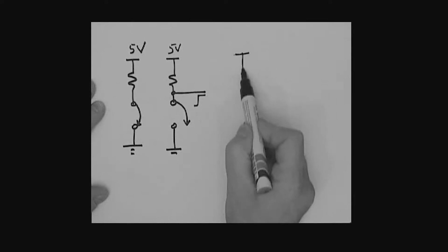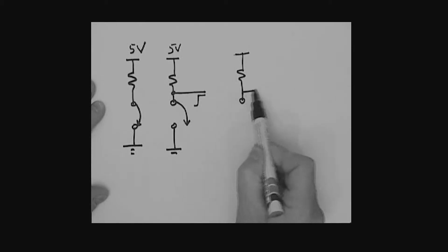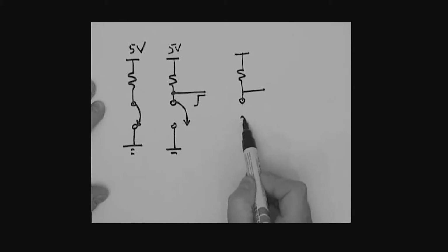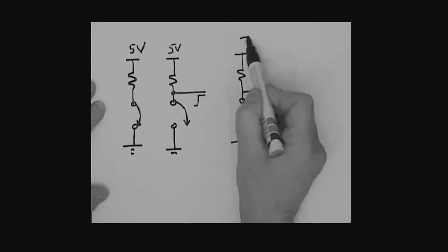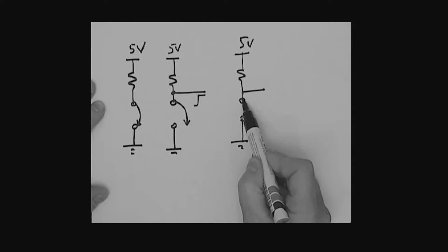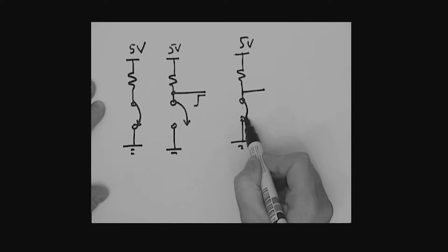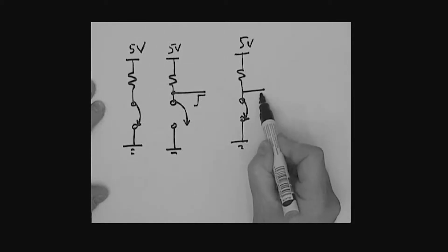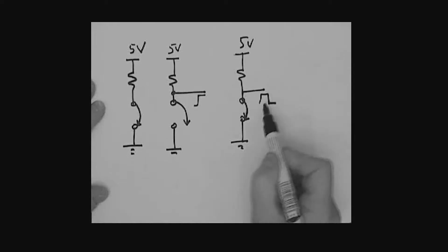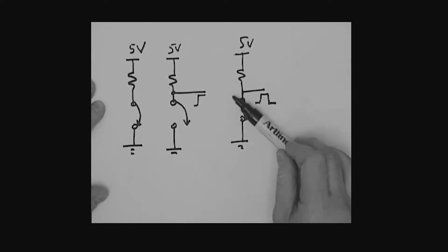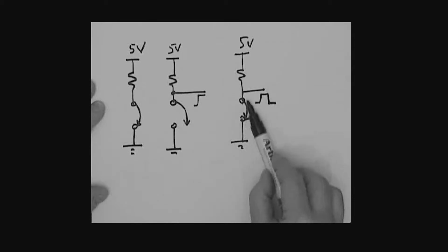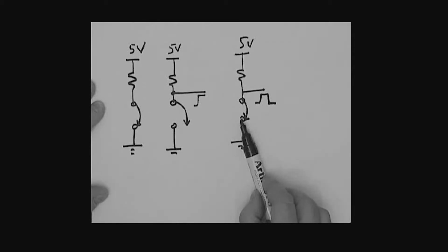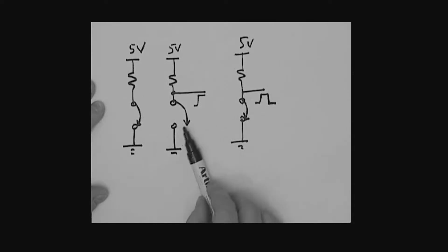And then what happens? Well, when we take our finger off the button, remember we're looking at this voltage here, what's going to happen next? Well, the terminal or the connector of the switch then goes back and makes contact like so. You might say, well, this has gone up and come back down to 0 again. But the problem is that when this little bar mechanism hits this terminal, it bounces up again. It's a mechanical problem. It actually bounces up again, and it becomes an open momentarily.